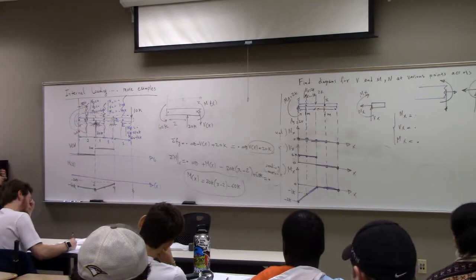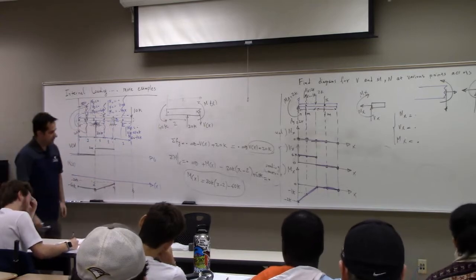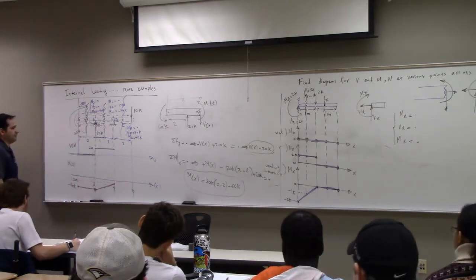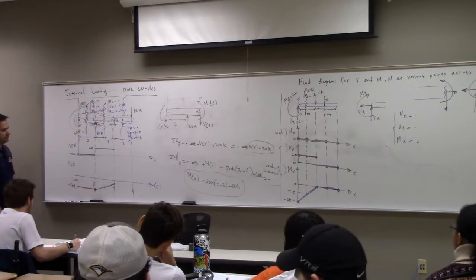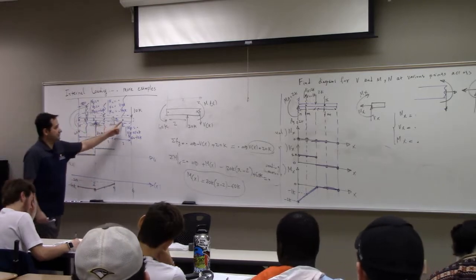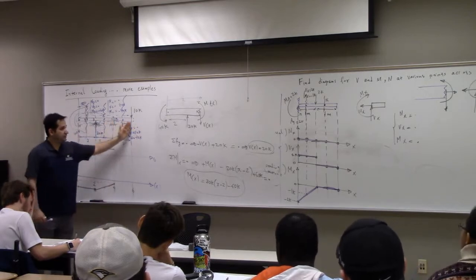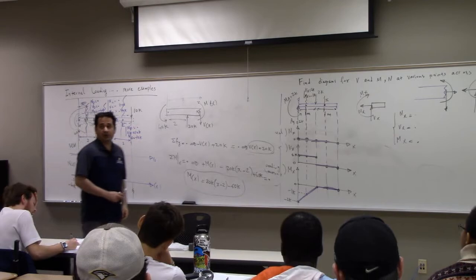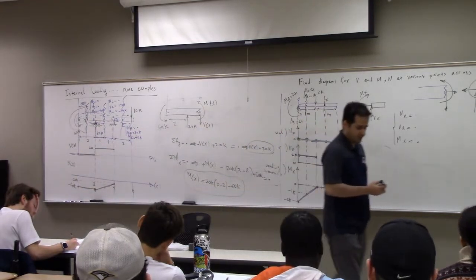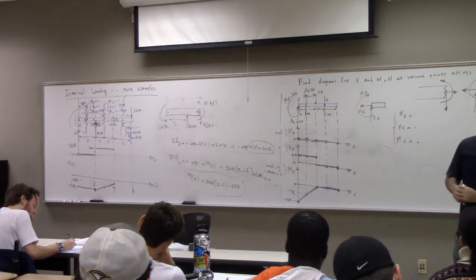So what about point between point, let's see, this is 2 plus 2, 4. Yeah, negative 20. Then you can do the same thing to draw the continuation of this curve from this point to the end. So when we talk about the shear moment diagram, we are actually more interested to see the range, not at a particular number.